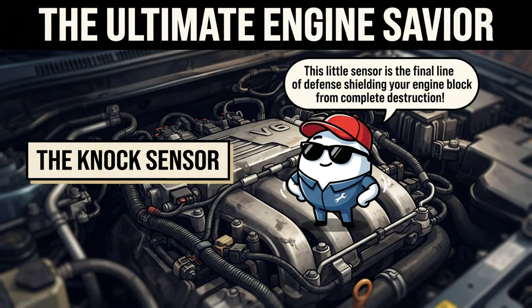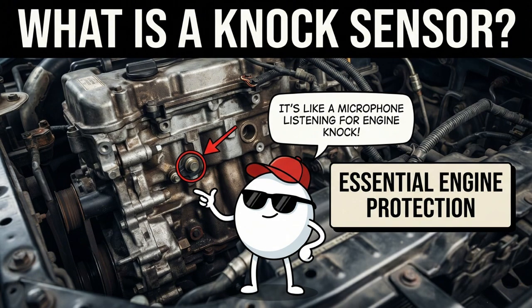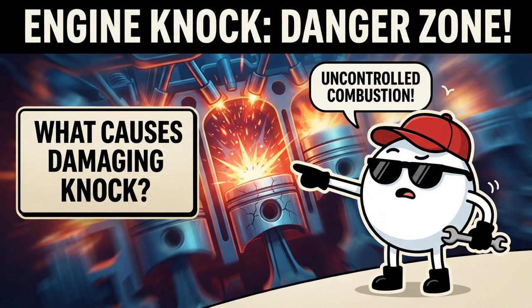The final line of defense shielding your engine block from complete physical destruction is the knock sensor. Bolted directly into the metal structure of the engine block, the knock sensor is essentially a specialized piezoelectric microphone tuned specifically to the high-frequency metallic vibrations of engine knock, or detonation. Knock occurs when unburned fuel ignites prematurely due to excessive cylinder heat, poor fuel quality, or advanced timing, sending violent shockwaves that can shatter pistons and snap connecting rods.